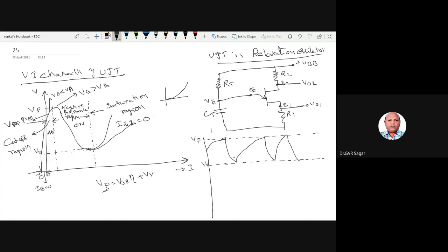So under this, the capacitor charging is given here. These are all capacitor charging, right? After getting fully charged, this peak voltage will fire the UJT according to this theory, right? Whenever the emitter voltage reaches the peak value, then the UJT fires, means switched on. UJT is switched on. So at that time it exhibits negative resistance, right? Means voltage is decreased. So the capacitor charge Vp is applied onto the emitter and UJT fires.